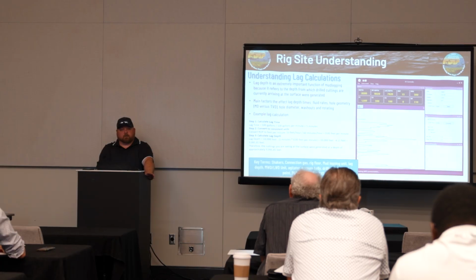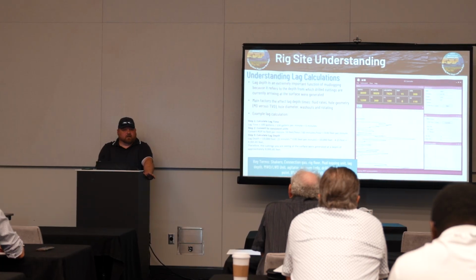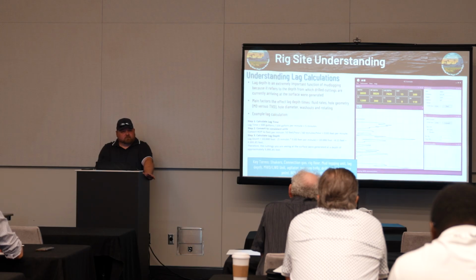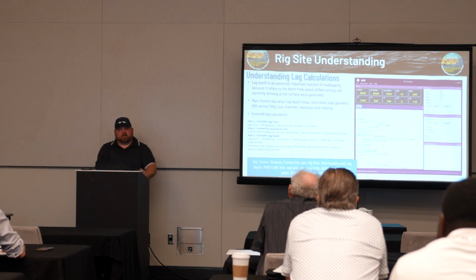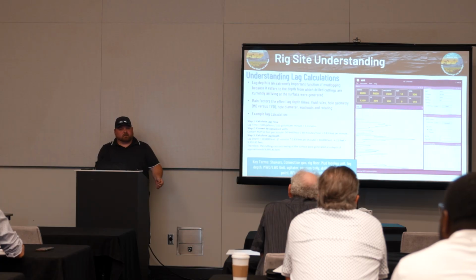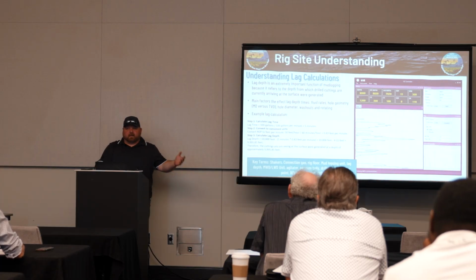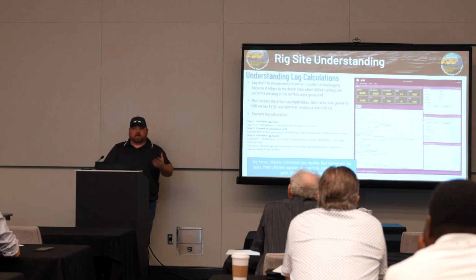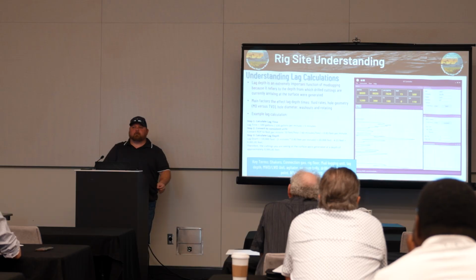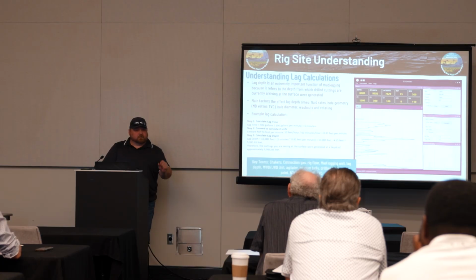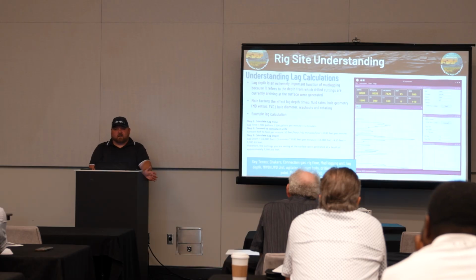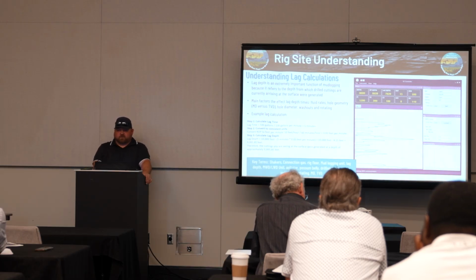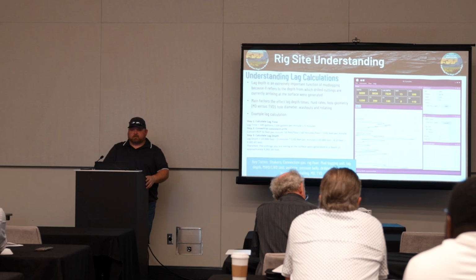We used to do carbide tests, which is unfortunately not allowed by OSHA anymore. So that's one way that we used to be able to calculate a lag. We'd drop a piece of carbide down the drill pipe, and it would create acetylene that we would read as it came back up the hole, and we could time that drop. Well, now we can use cellophane or little short grain rice. You can use it and see it come back up. Typically, it's just easy to watch a sweep. They know when they pump a sweep, they know when it should come back, and you calculate it from there. And a sweep with the drilling fluid is easy to see coming back.